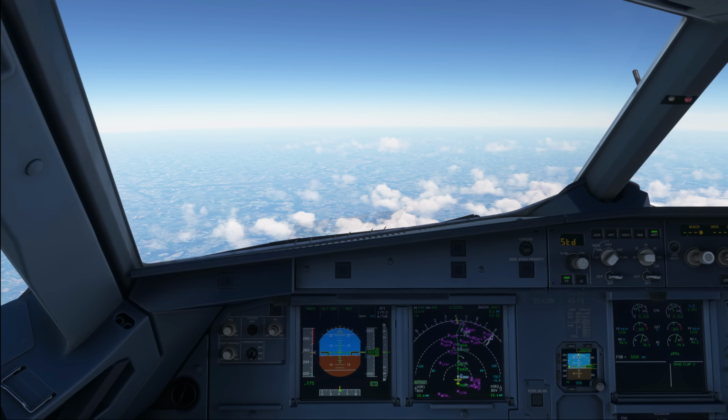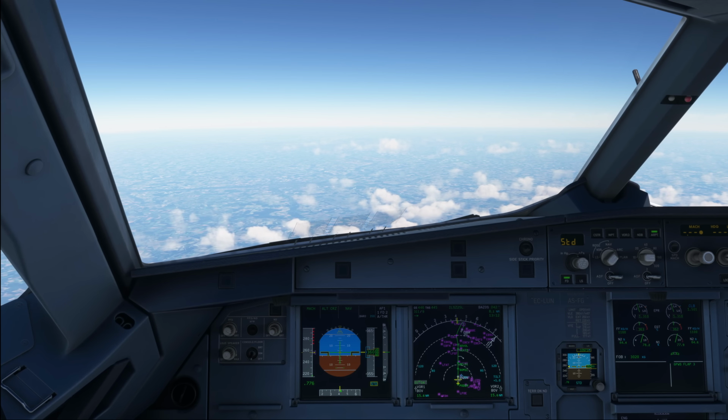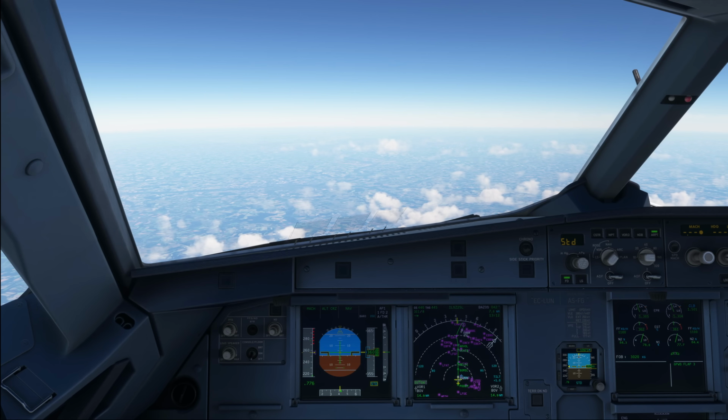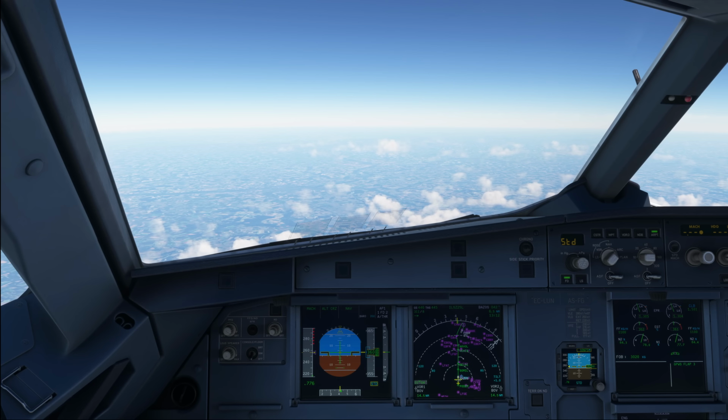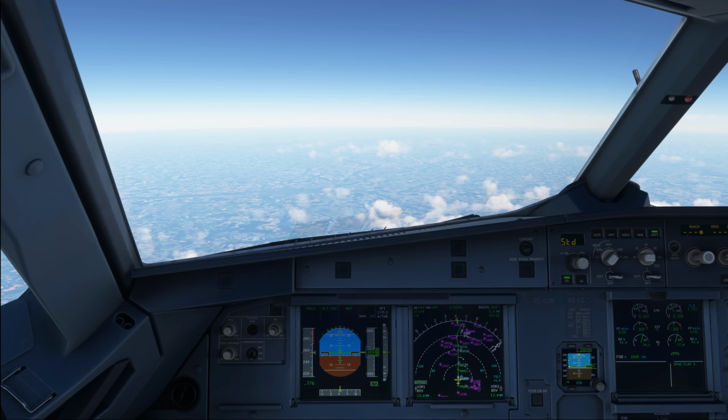On the approach then, when conditions and air traffic control permit, a decelerated approach should be flown as it reduces fuel consumption. And decelerated approach basically means maintaining config 1 until about 2,000 feet above ground, then go config 2, gear down, config 3 in order to stabilize the airplane. When the approach type does not enable to fly a decelerated approach, the flight crew should fly an early stabilized approach, which means being in landing configuration by the time you pass the final approach phase. When landing performance permits, the selection of config 3 reduces both approach time and fuel consumption.